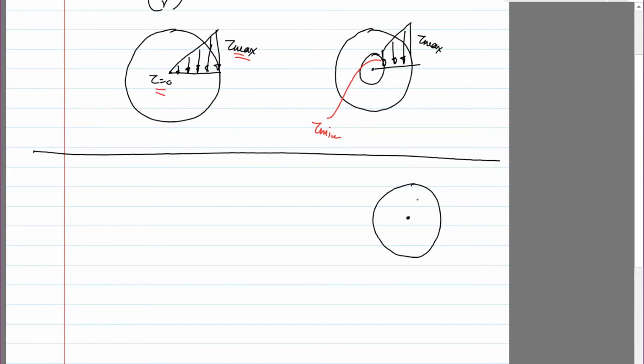cylinder, the cross section, and take a small element which is at a distance of rho from the center, which is now the radius. The shear strain is going to be something like that. And this element has an area of dA. And of course, this thing is subjected to a torque T. Now, the total torque is going to be, so the torque basically induces shear strain. So if you think of it, if you have a surface and you hold it and you twist it, then that whole surface is going to develop a shear strain, a shear stress.